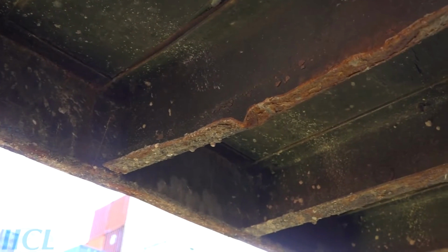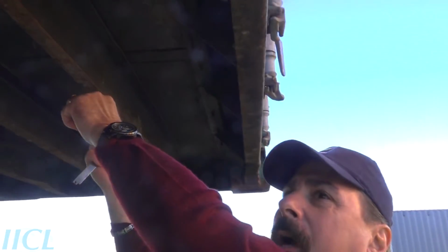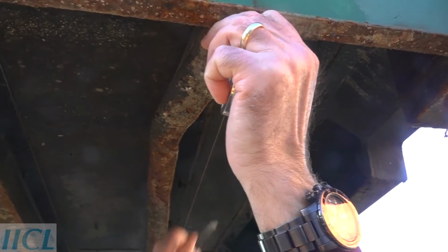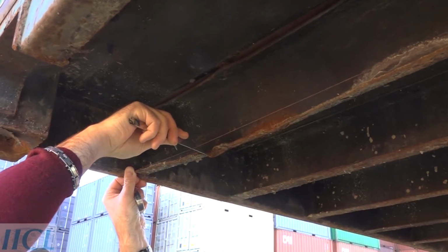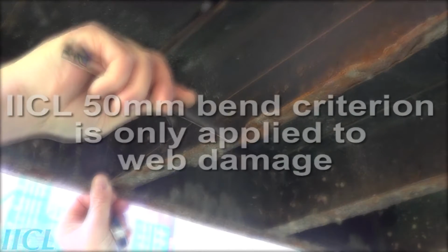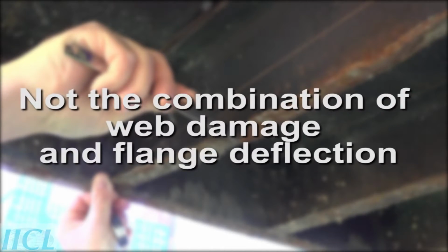When the crossmember is bent from the flange side, the string line is placed at the inner radii of the lower flange at the undamaged ends, and the measurement is made to the inner radius at the point of maximum deformation. This ensures that the IICL 50 mm bend criterion is only applied to web damage and not the combination of web damage and flange deflection.